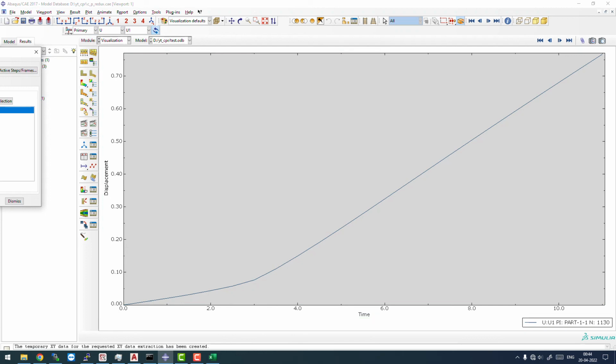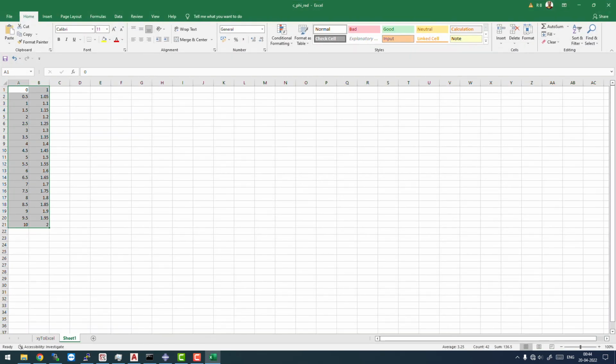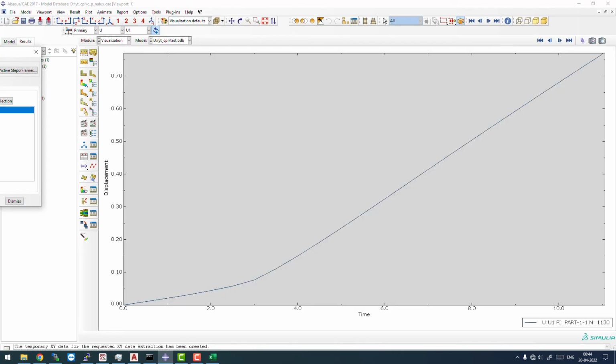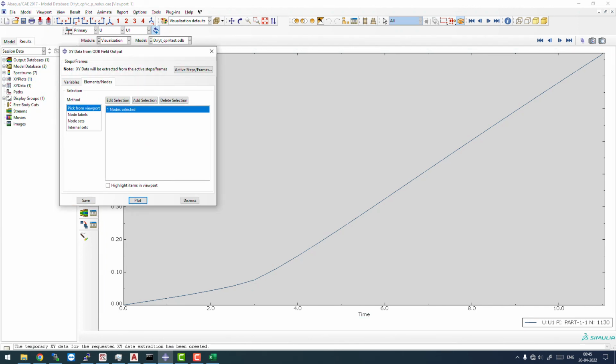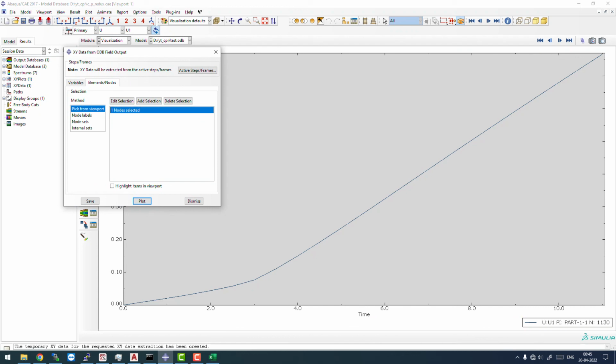So at the point value of 0.3 you can check that the factor of safety or reduction factor is 1.3. So for this you can assume the factor of safety of 1.3. Further, you can do a much finer analysis based on your own calculations, and based on this tutorial you can create the Excel sheets and the text file which you want to insert in your own input file. So I am going to finish my tutorial here.